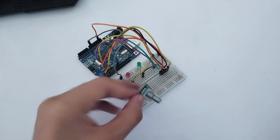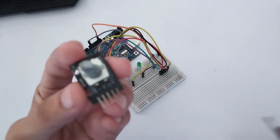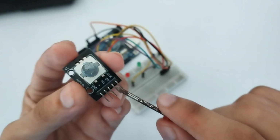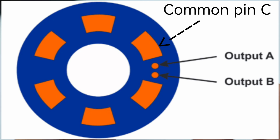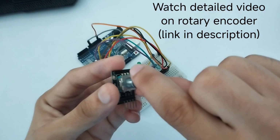Now let us discuss the pinout and the internal structure of this rotary encoder. In this encoder, as you can see, it has 5 pins, right? Clock pin, which is represented by letter A, DT pin, which is represented by letter B, switch pin, VCC and the ground. And in this image, as you can see, it has 3 pins, A, B and C, right? So A and B remain fixed, but the common pin C comes in contact with the pins A and B whenever we rotate the knob of this encoder clockwise or anti-clockwise, right?